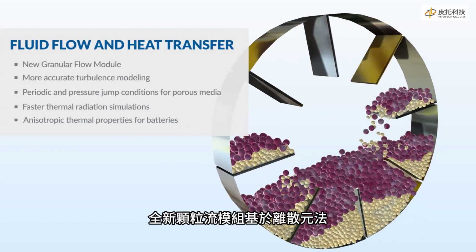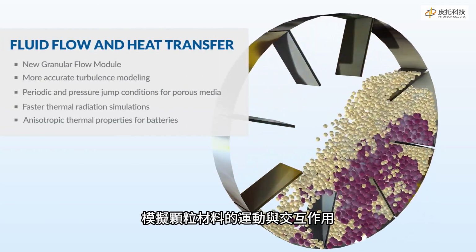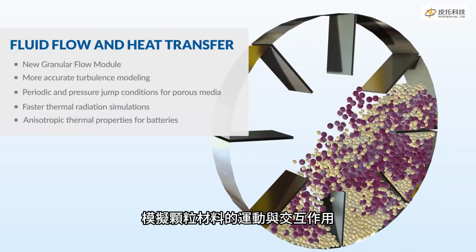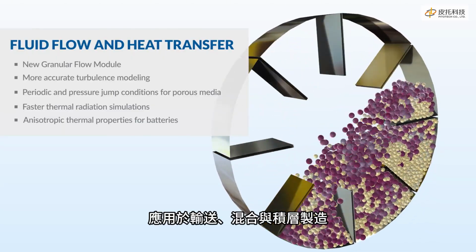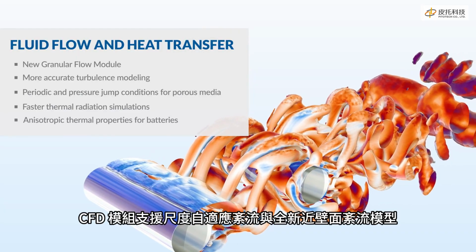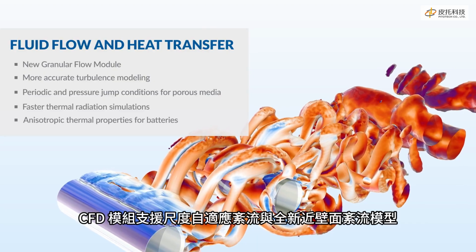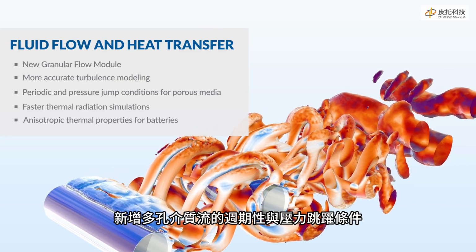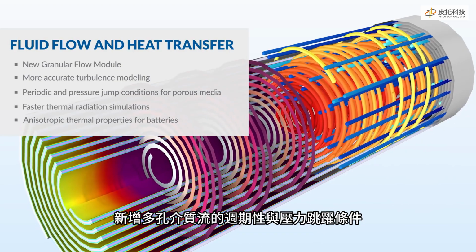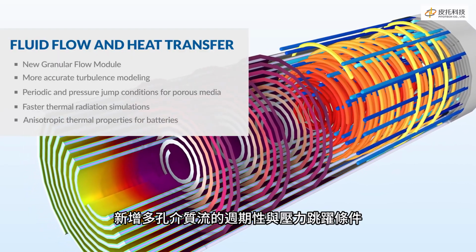The new Granular Flow module, based on the discrete element method, simulates the movement and interaction of granular materials in processes such as conveying, mixing, and additive manufacturing. The CFD module now supports scale-adaptive turbulent flow simulations and a new turbulence model that improves accuracy near walls. Additional updates include new periodic and pressure jump conditions for porous media flow.